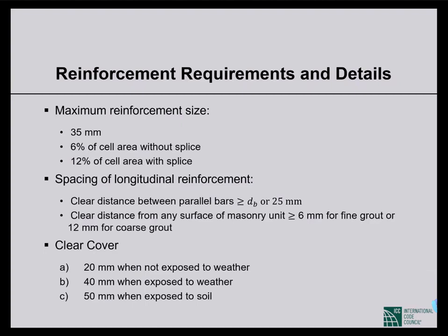And the maximum amount of reinforcement that we can use in a cell is 6% of the cell area without splice. If we use splice for lapping purposes, we can double this percentage of reinforcement to 12%.